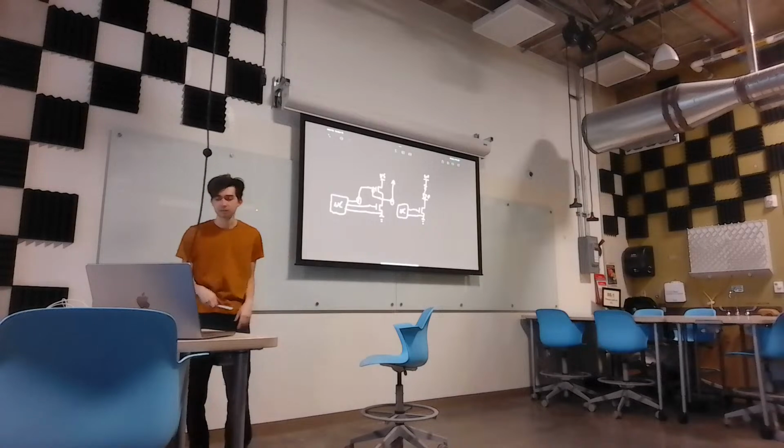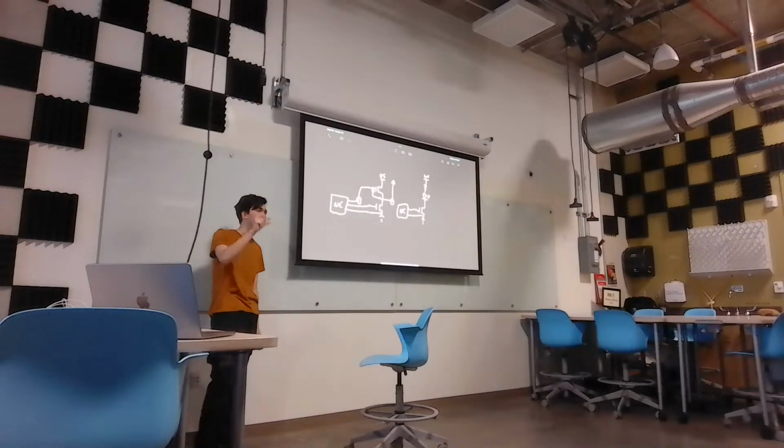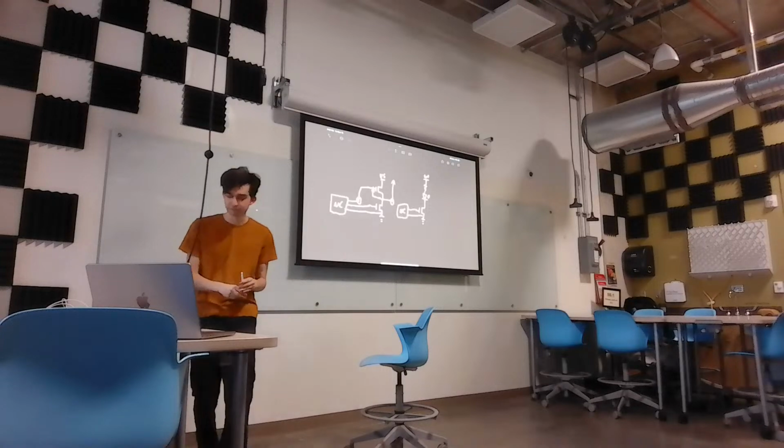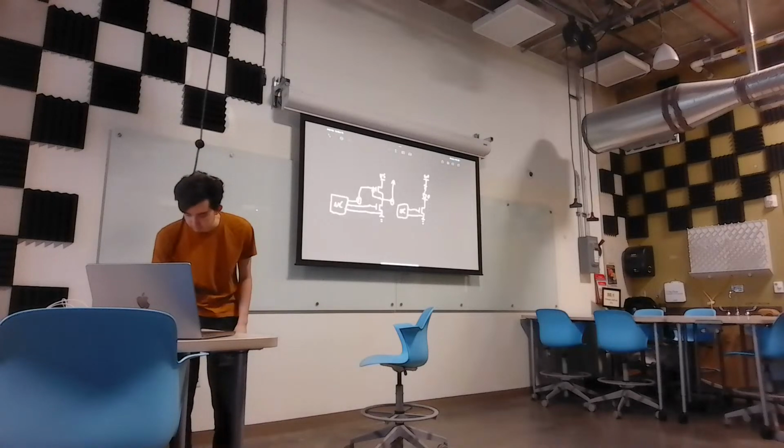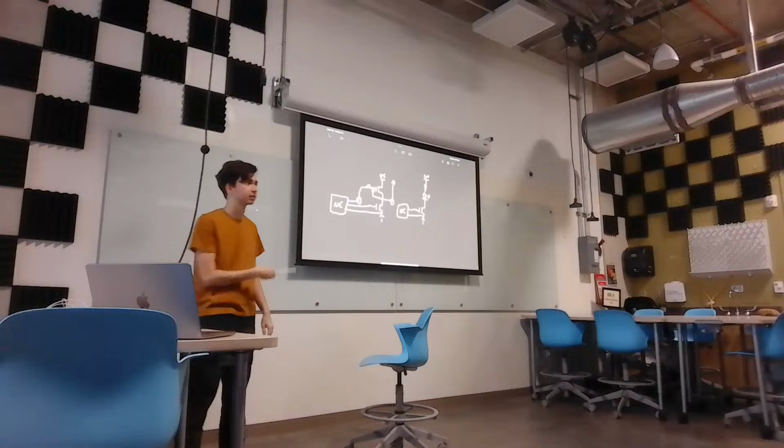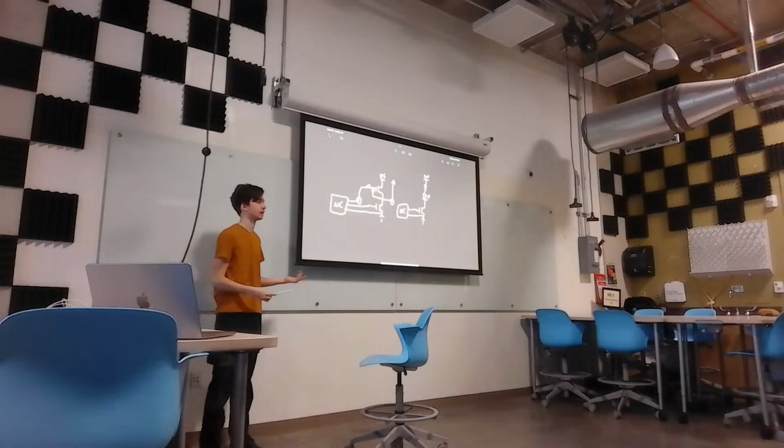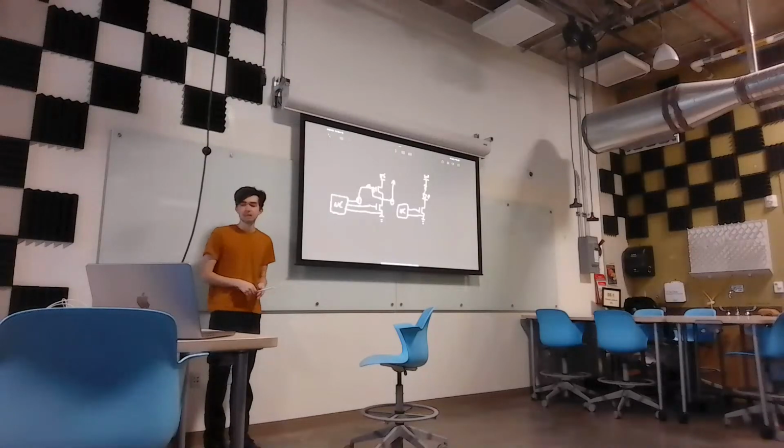So when this MOSFET turns on, that capacitor is all good. It's holding that voltage there. And then when you want to turn the FET off, you have something reconnect here and suck the voltage out of the capacitor, and it turns off. So it's like a flying power supply. This capacitor is just there to hold the voltage on that FET.